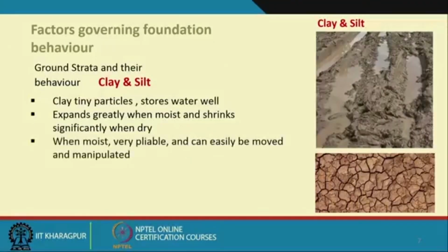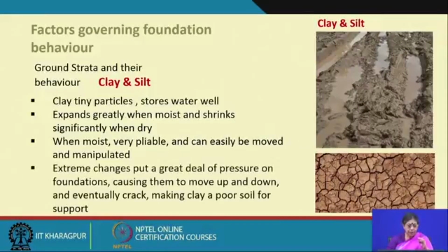When moist, it is very pliable and can easily be moved and manipulated, but extreme changes put a great deal of pressure on the foundation, causing it to move up and down and eventually crack, making clay a poor soil for support. And there probably what you need is a different type of foundation, and if that is not there and originally it has not been built, then some sort of problem can happen.